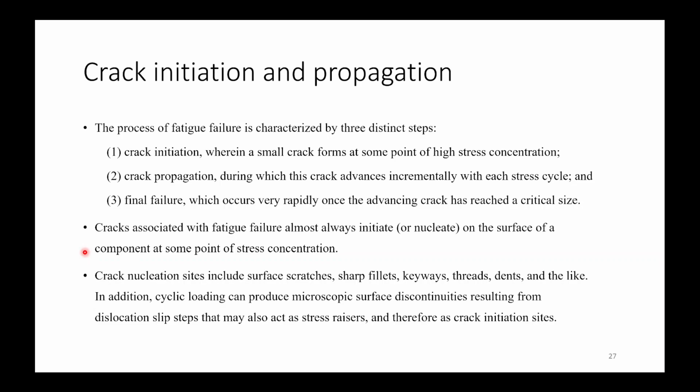Now cracks associated with fatigue failure almost always initiate on the surface of a component at some point of stress concentration. Crack nucleation sites include surface scratches, sharp fillets, keyways, threads, dents, and the like. In addition, cyclic loading can produce microscopic surface discontinuities resulting from dislocation slip steps that may also act as stress raisers and therefore as crack initiation sites.